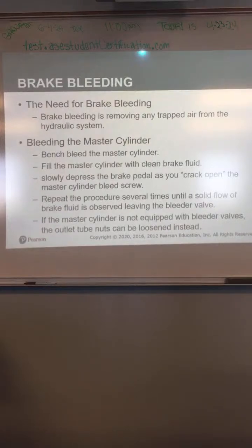If you're going to replace the master cylinder, we talked about this yesterday, bench bleed the master cylinder before you put it on. Fill it with clean new brake fluid. Slowly depress the brake pedal as you crack open the master cylinder bleed screw, which it probably won't have. Some do, some don't. Most master cylinders don't have their own bleed screws. You just use that little plastic tubing and the fittings they give you with the master cylinder. We looked at that yesterday. Repeat the procedure until you get a solid flow of brake fluid leaving the bleeder and you don't see any air bubbles. If it does not have bleeder valves, the outlet tube nuts can be loosened instead.